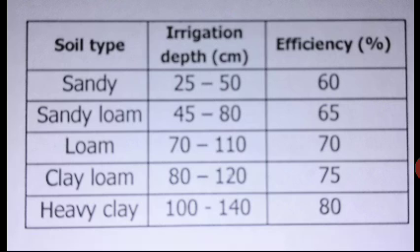So what is gross command area? GCA means gross commanded area. It is defined as the gross irrigable area which can be commanded by irrigation. The boundary of GCA is usually defined by the drainage on either side across which irrigation cannot be extended economically.